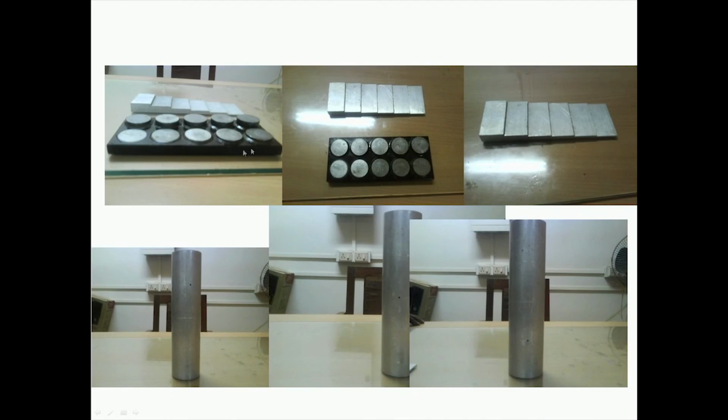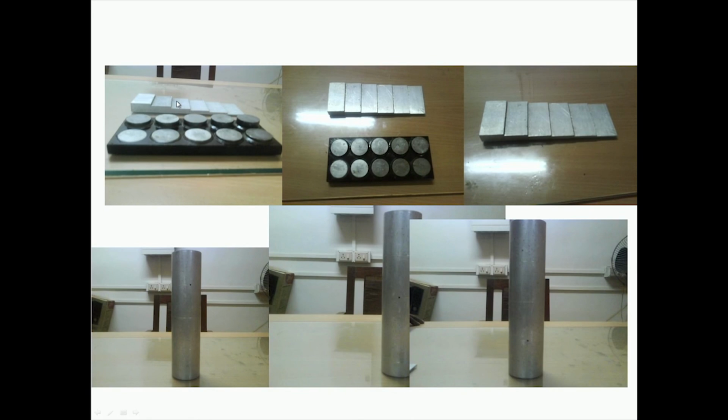Then you could have this kind of blocks also. For example, if you see this one over here. This is having several steps like this. These steps have different thicknesses. So, that means this kind of block can be used for thickness calibration. In cases where you know that there is some material loss or material thinning, and if you want to inspect that kind of damage by using ultrasonic testing, then these kinds of blocks are quite useful to calibrate the instrument before you do that test.